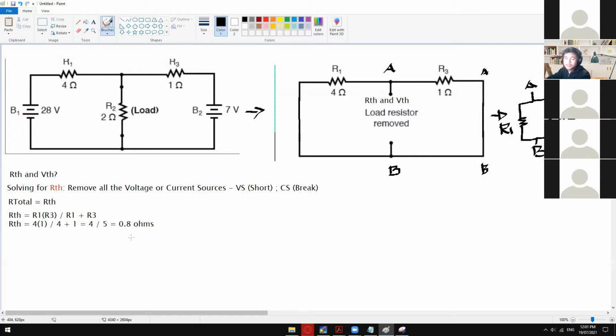as your RTH. So the same scenario, if we have, let's say, the R load in here on the bottom part, so we have node B right here and then node A. This one will form a series connection, R1 plus R3. So that really completely depends on the placement of your R load. I hope we're clear with that. That depends on how you analyze the circuit. Are they in series, are they in parallel, etc.